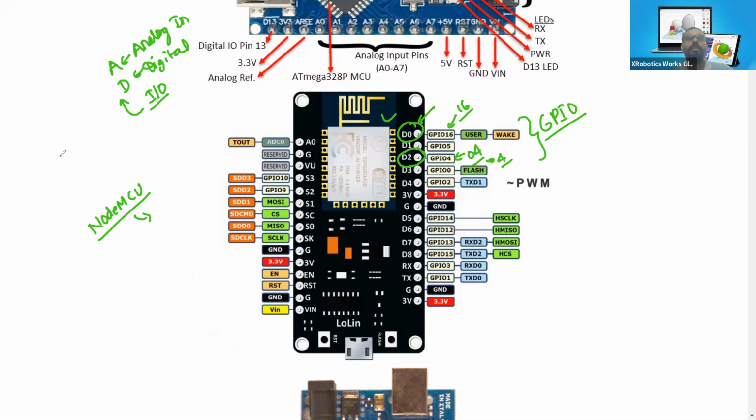Remember last time we did the sample programming, in which we declared the pin mode under the setup. So under the pin mode, we always declare the pin numbers like 4 or 5 or something like that, based on the input and output condition. So in place of this 4, we will utilize the 16 or 4 or any other pins mentioned in the specification sheet rather than the D4.